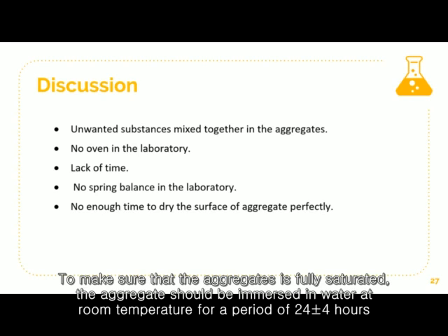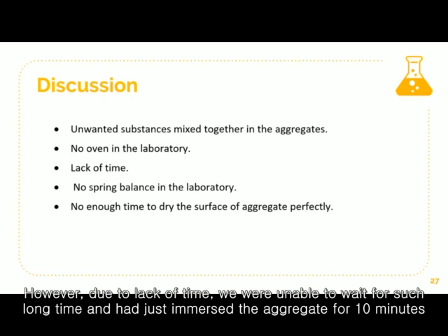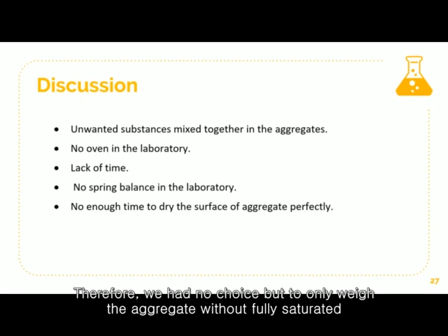To make sure that the aggregate is fully saturated, the aggregate should be immersed in water at room temperature for more than 24 hours. However, due to lack of time, we were unable to wait for such a long time and had just immersed the aggregates for 10 minutes. Therefore, we had no choice but to weigh the aggregate without it being fully saturated.